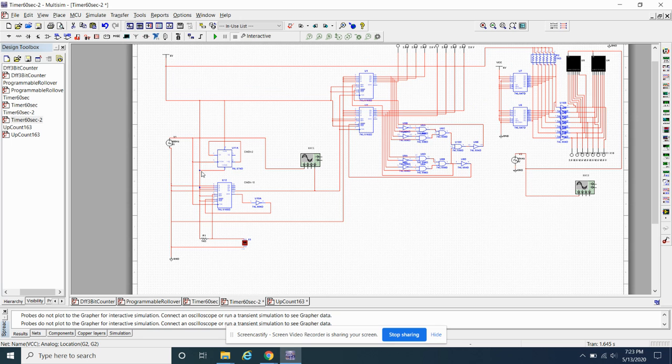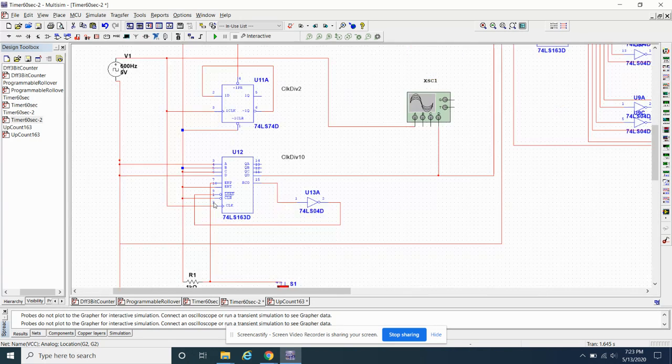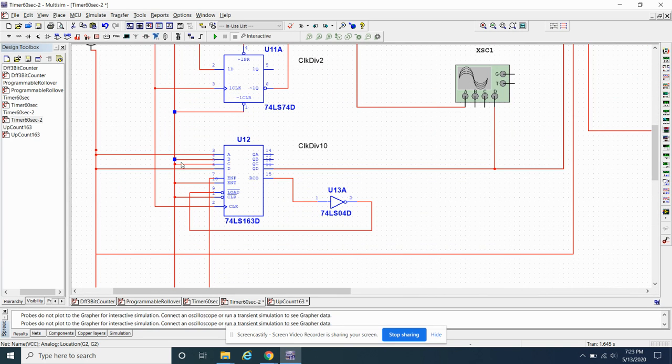If I follow that line all the way down, that's VCC. And that's a 1, that's a 1, and then this one here is also tied to this line here, which is ground. So 0, 1, 1, 0, right? So D is the most significant bit, that's a 0. I have a 1, 1, and then the least significant bit is a 0. And if you do 0, 1, 1, 0, that's a 6.